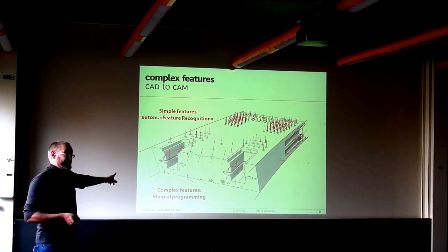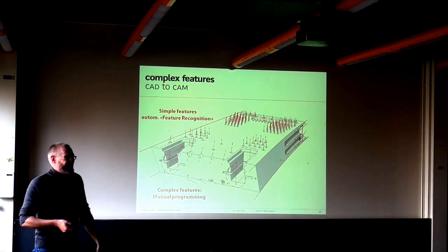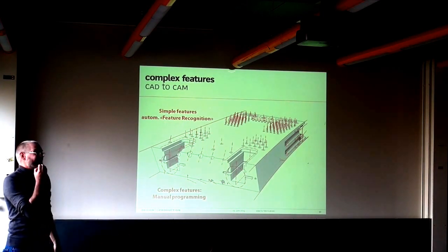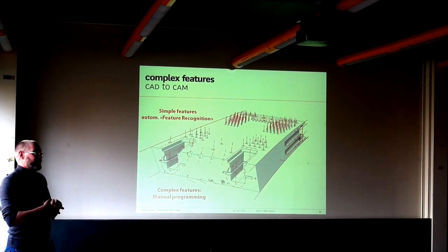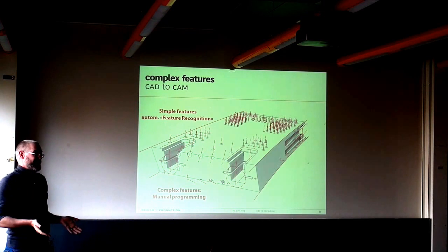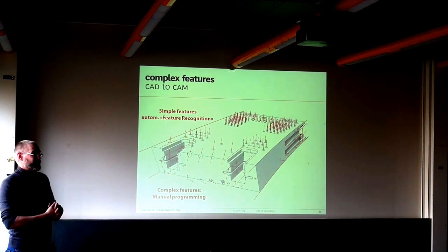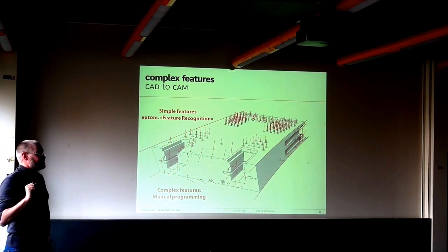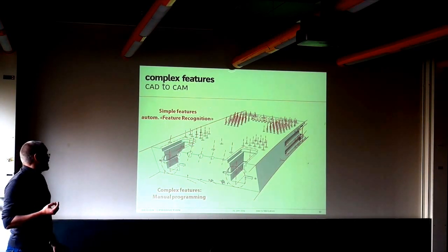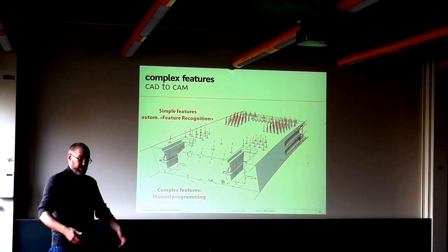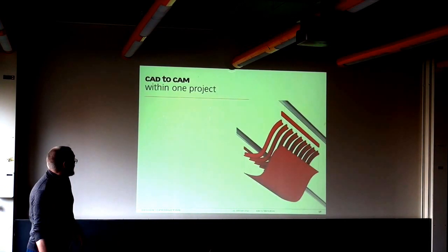And then it's getting meshed anyway to do the renderings. It makes no sense. It makes much more sense to say, hey, I know this comes into being by drilling a hole there, which is a very shallow hole with a very large diameter, and 90% of it is cut away afterwards or beforehand with a circular saw blade this size. I don't need this final 3D model of the thing, actually, only for showing off. What I need is the machining information that I can hand over to the CNC mill to do things like that. And this is what we're doing.